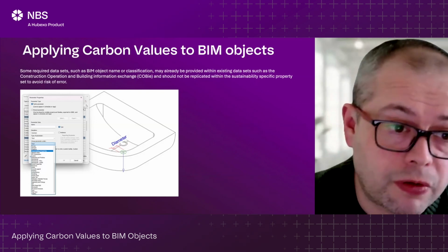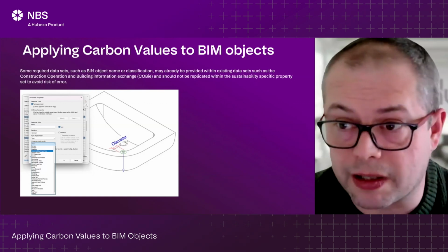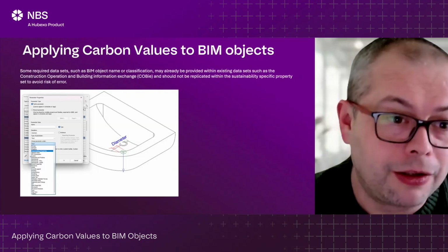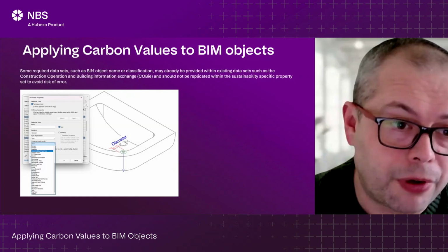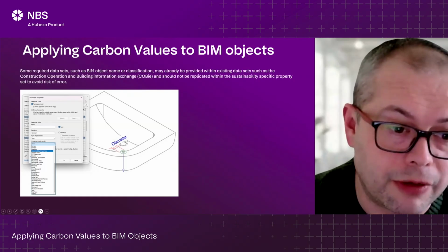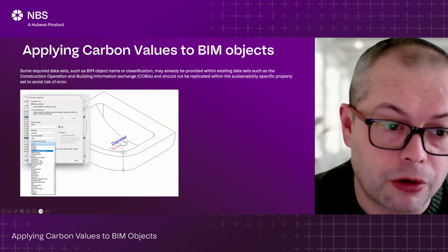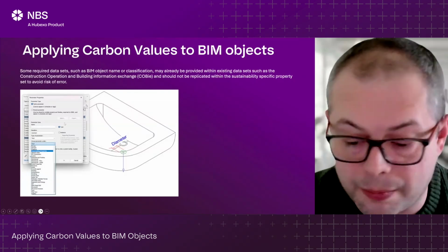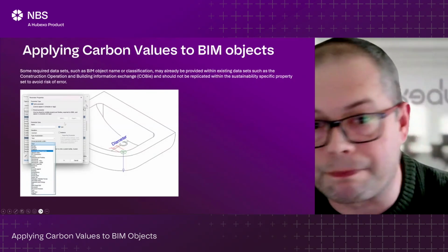In Revit, we've got some screenshots here. Apologies for the visibility on this, but it is a screenshot taken direct from the screen. You can go into the parameter properties and you'll find green building properties in the drop down on where to group the properties under. Give them the name, set whether it's type or instance, whether you want to report on that or not.